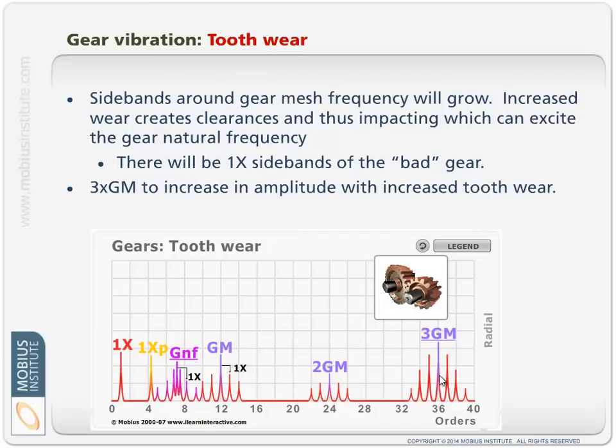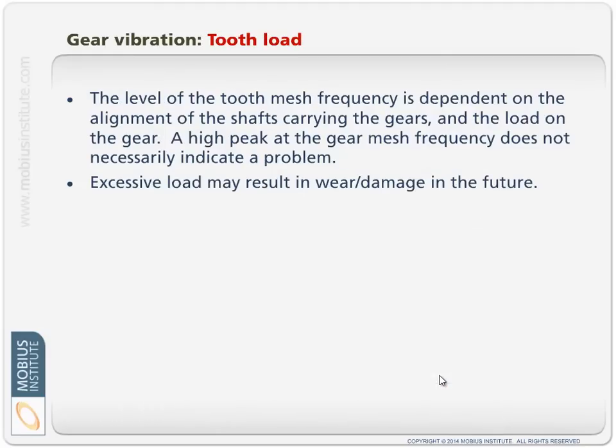So obviously with tooth wear, there should be clear signs in the lubricant. The root cause may also be present in the lubricant as well. Maybe the viscosity is incorrect. Maybe the wrong lubricant has been put in there. Perhaps the lubricant is contaminated with water or with particles that's causing that wear to occur.